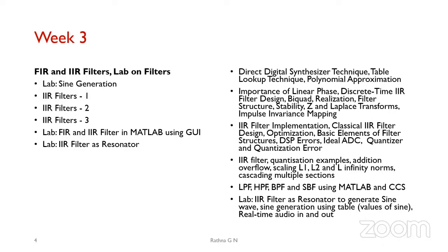So we have seen using MATLAB how you can use the filter design toolbox to generate your low pass filter and high pass filter, and see their characteristics: whether you want linear or non-linear phase, which you can accept, and whether it is a stable filter in the case of an IIR filter. Once you get the coefficients, you'll use them in your Code Composer Studio. As a lab session, as a resonator, we can have it in oscillation mode to generate a sine wave.